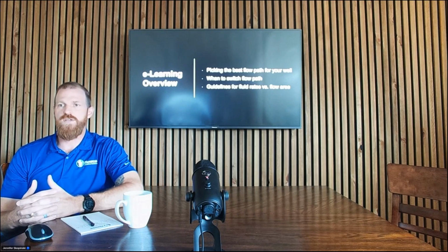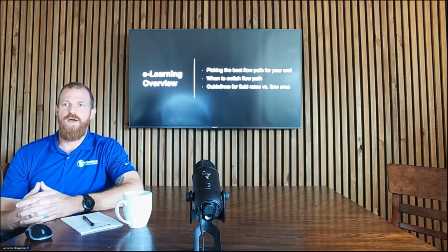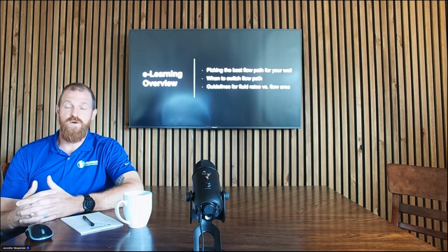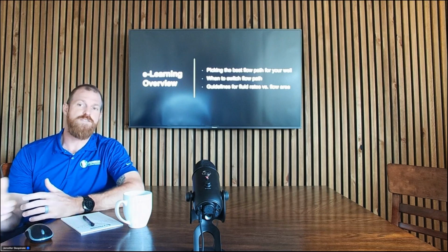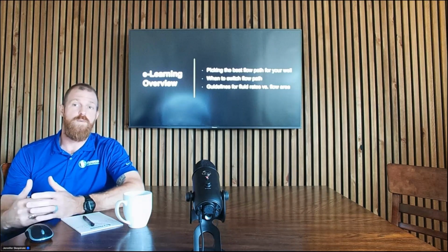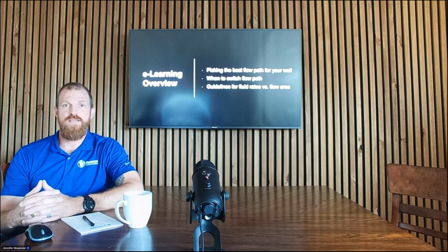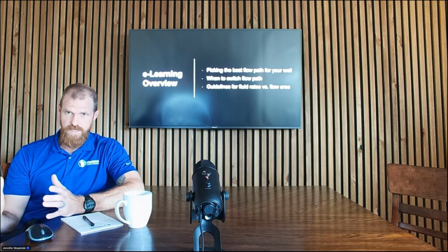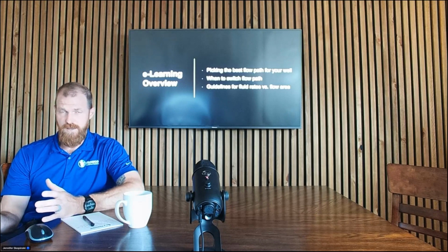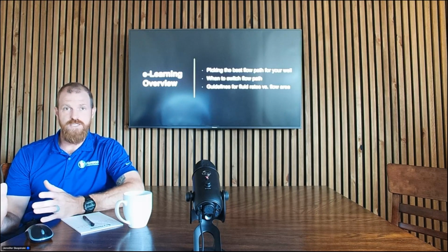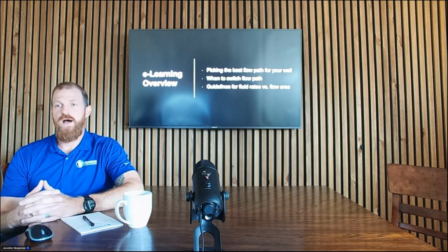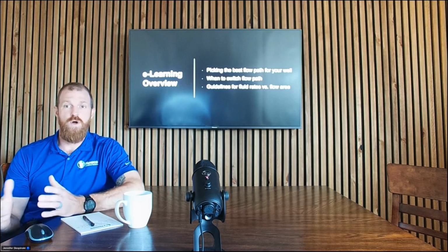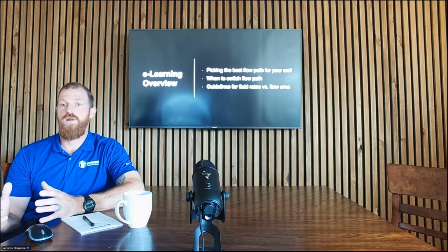But ultimately, what we want to talk about today is picking the right flow path for your well. And there's a couple different ways to look at it. Primarily, what we'll talk about today is picking your flow path specifically to maximize production or minimize flowing bottom hole pressure. So that's the main purpose: what is the best flow path to put in the well today to help maximize the production out of the well, to achieve the lowest flowing bottom hole pressure, those type of focus points.